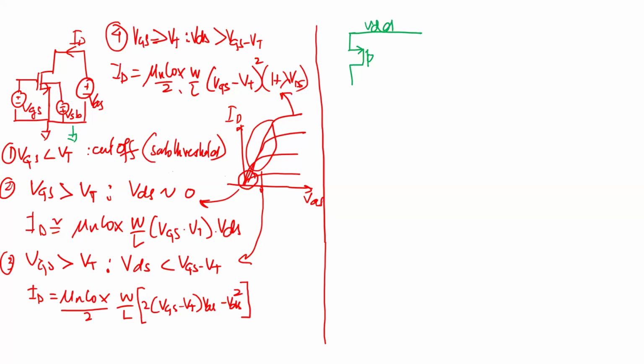Actually, I like that because that way at least it shows you have a PMOS. So the bubble actually is good because that makes the source and drain terminals symmetric, right? The arrow tells you that that's the source, but it's not physical in that sense. As a designer, you want to make sure whichever is your source, you want the arrow to be in that direction. If you flip it, nothing is wrong. You'll pass LVS, it'll work fine. It's just confusing and not a good way to do the schematic.